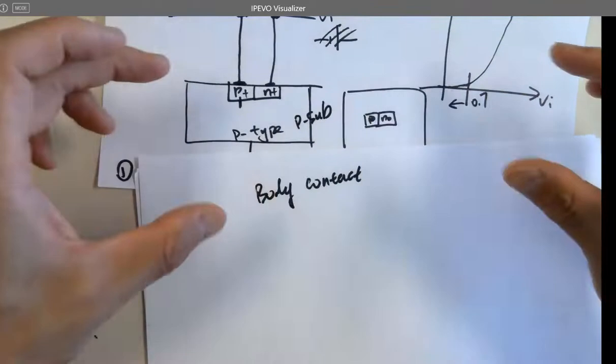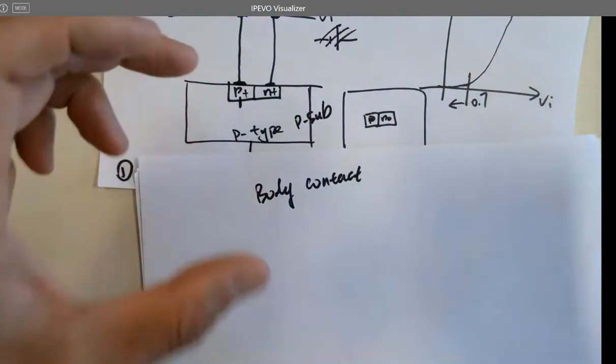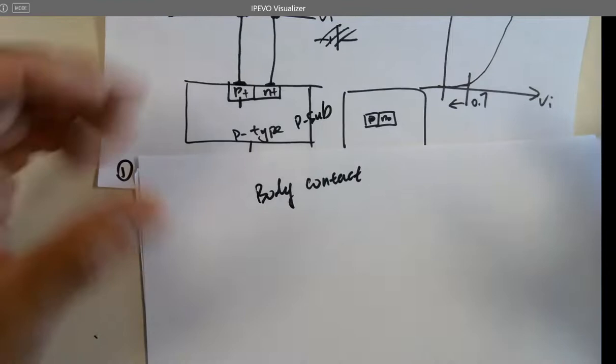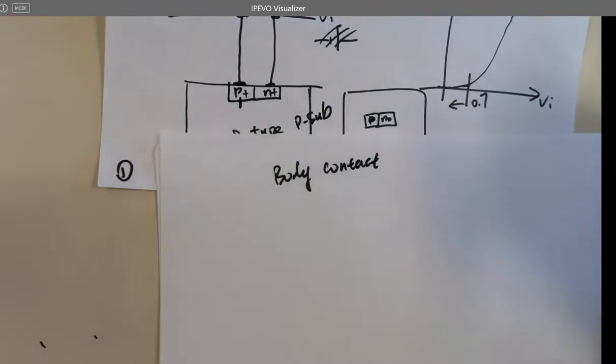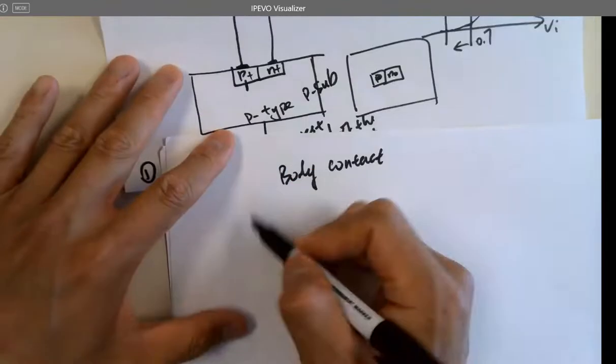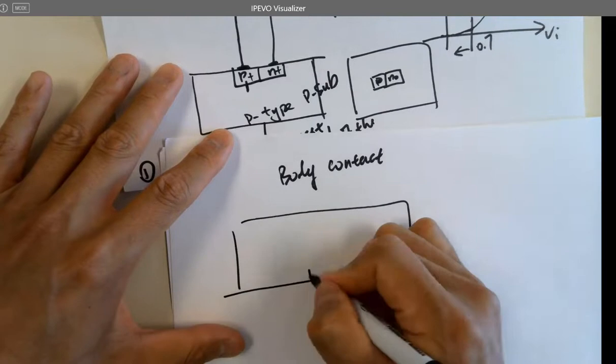Also, the substrate in integrated circuit design is also called the body. That's the body of the chip. So that's why this P plus connects to the P sub.